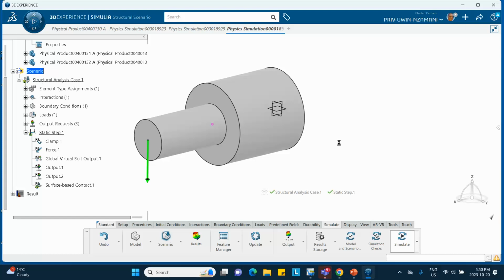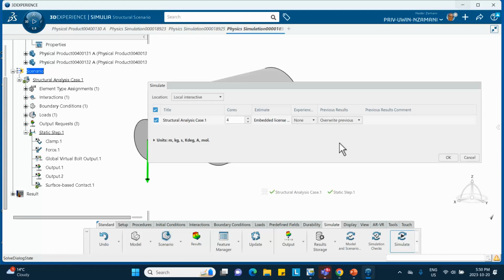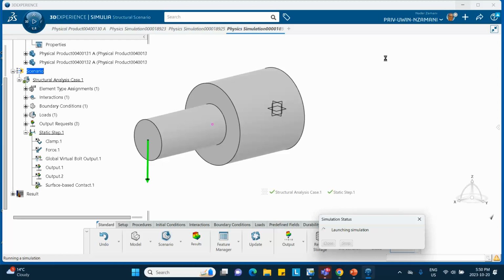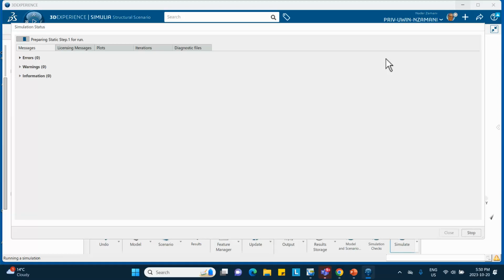So we are using the good old meshes that we created for this assembly. And I told you why you may do that. Because meshing is an expensive proposition. A good mesh can be expensive. You already meshed something that you like. Now, if you wanted to go and create another mesh, and we will, after this thing, I'll show you, what if you want to ignore those meshes? What if you want to do it again at the assembly level? It can be done, but you have to pay the price.